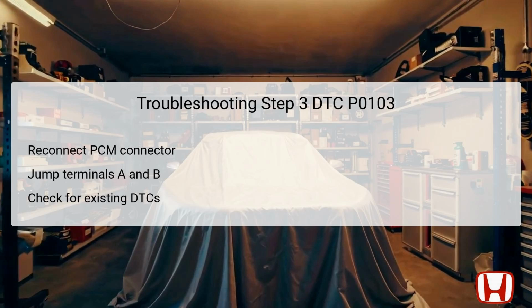After establishing this connection, turn the ignition switch to the on-2 position again, or press the engine start-stop button to activate the on mode. Clear any existing DTCs using the HDS and then check for both pending or confirmed DTCs.